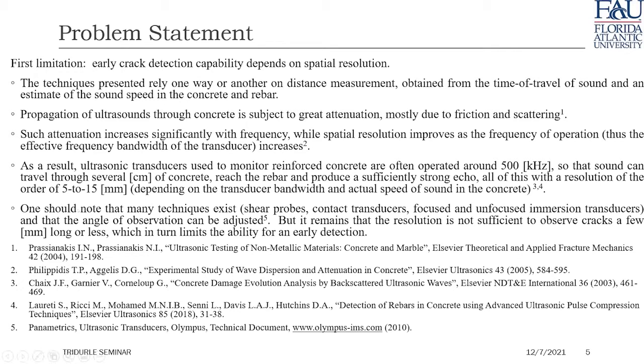Another thing to note is that many techniques exist, such as shear probe, contact transducer, and focused and unfocused immersion transducers, and that the angle of observation can be adjusted to obtain better results. But it remains that the resolution, no matter what, is really not sufficient to observe cracks a few millimeters long or less, which in turn limits the ability for early detection.